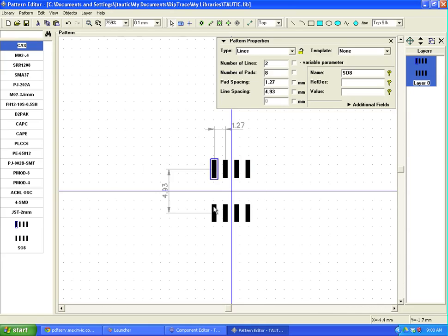And you can see things are looking a lot better. All right, now let's see here. Just as far as pad numbering, let's say this was actually facing vertical. Of course, this would be pad number 1. If I hover over it, you can see that this is in fact pad number 1, pad 2, pad 3, pad 4. Hop up here, pad 5. So this is numbered just like the component will be. So that's really all you would need to do to set up a basic footprint.